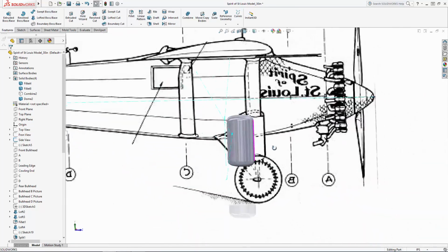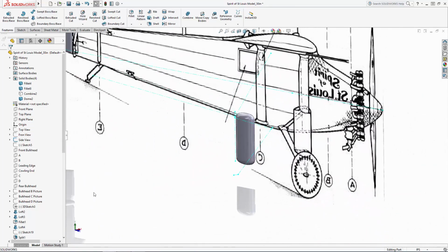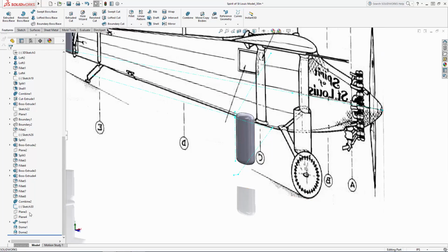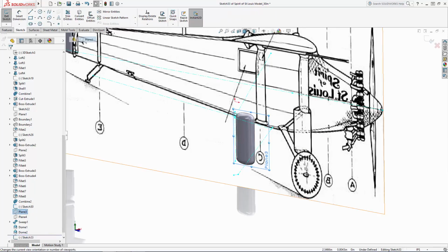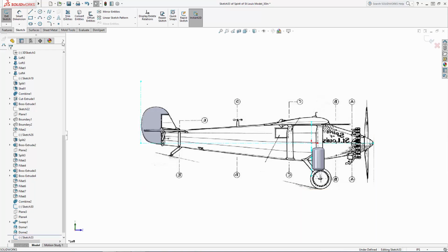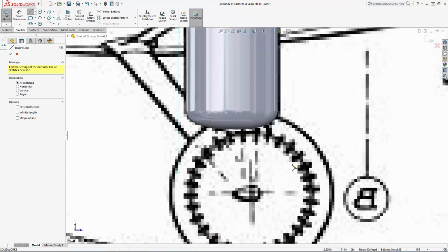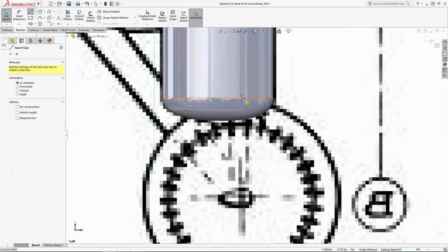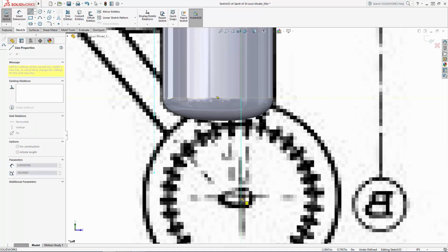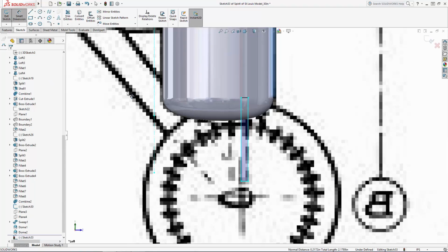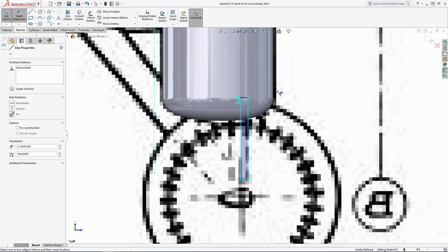Let's add the main landing gear strut to the bottom of this fairing using the Revolve tool. Sketch on the vertical plane we created that goes through the center of the fairing, and I'll sketch a simple rectangle with the center line of our revolve going through the center of the wheel. I'll go ahead and dimension this sketch to constrain it.